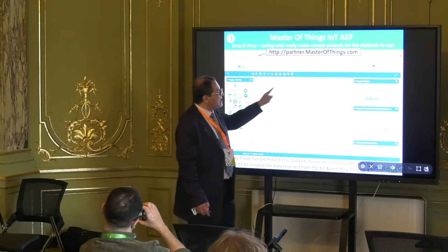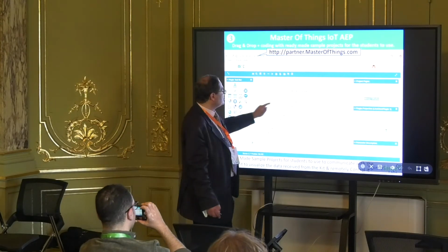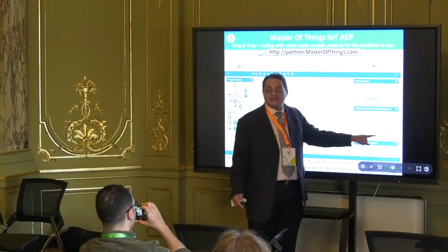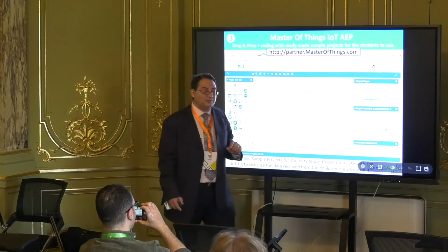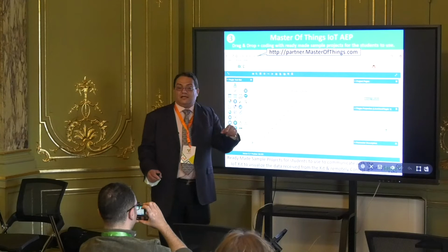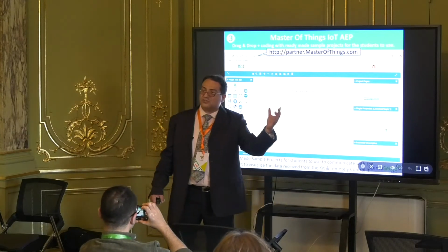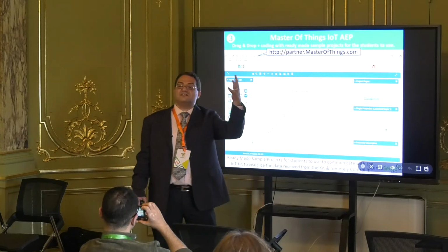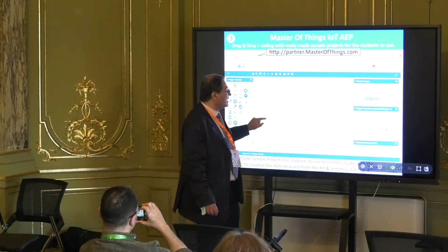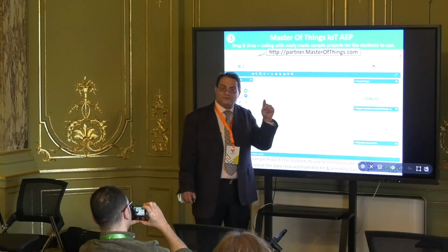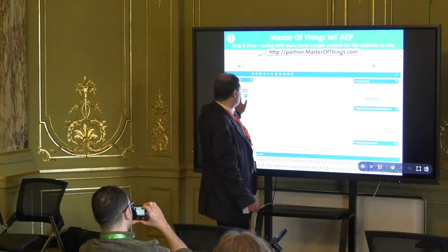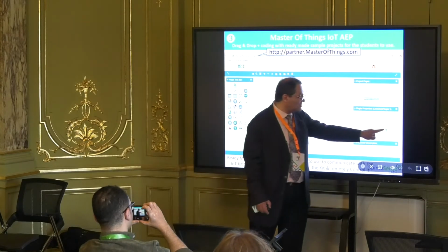The idea is that you design your page here, you drag a line chart, for example, you put it here, you play with the size and colors of the chart in the plugin properties here, and the most important property is what data would be displayed in this chart. Now, if you have your mobile phone, which has a temperature sensor, or if you have an IoT device, which has a temperature sensor, and you would like to display the temperature value in your city location versus the time, how do you do this? You put a line chart, and then you go for the data source.